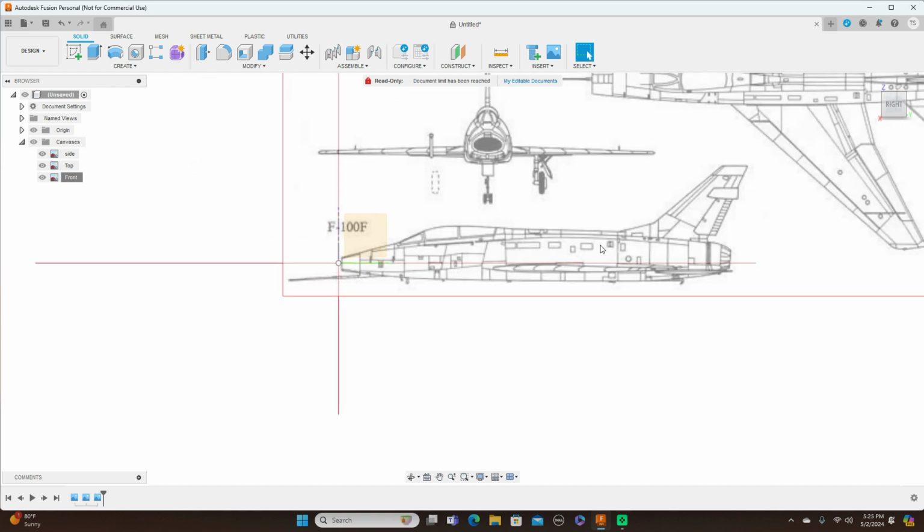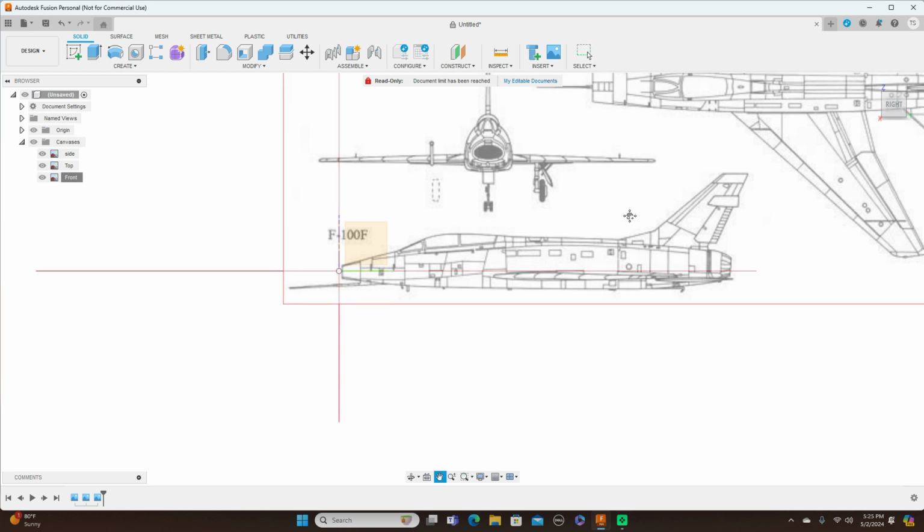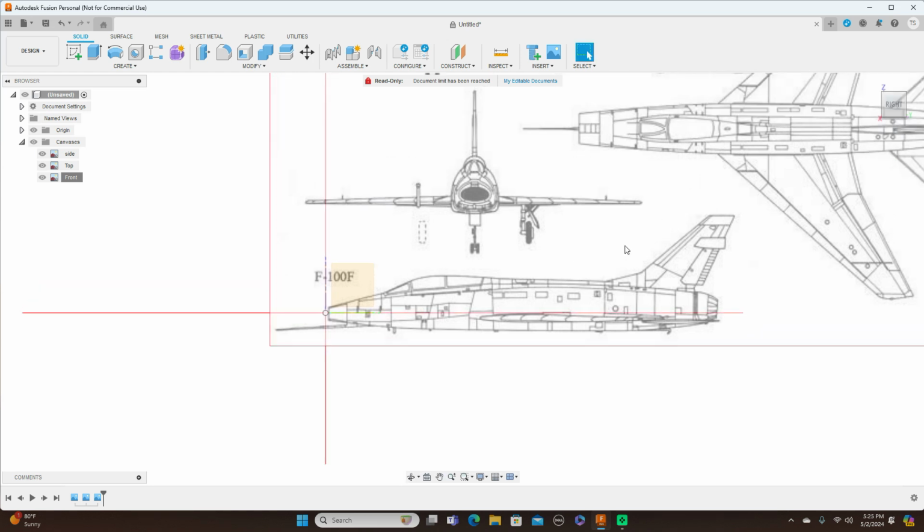Okay, now I'm going to use a cylinder shape for this because this is sort of round right here. And I can always flatten the bottom out on the cylinder. And again, if you have the formers for this, you can go ahead and use the formers and loft this all the way through with one body because there's nothing complex in here.